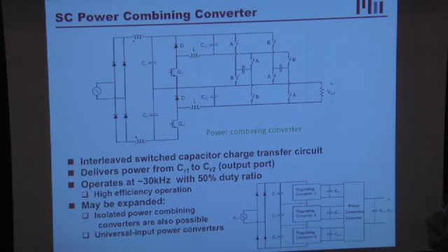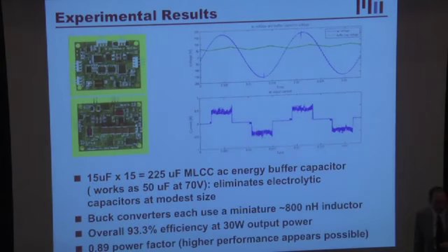The benefit of a switched capacitor technique is that you can get very high power densities and very high efficiencies, but they can't regulate. That's a circuit design trade-off in these devices. So we're going to use the first stage to do the power factor control and the regulation, and the second stage to just shuffle energy among the two outputs to combine it to a single output, okay?